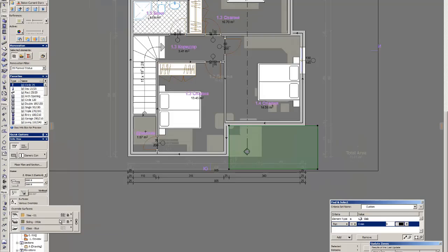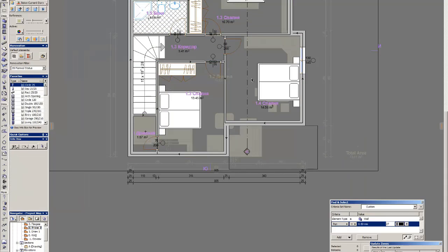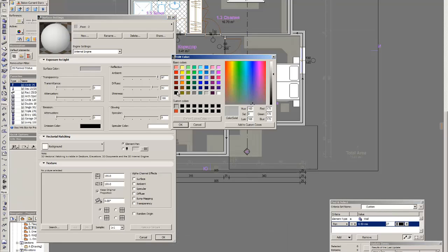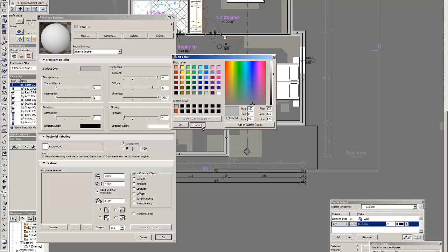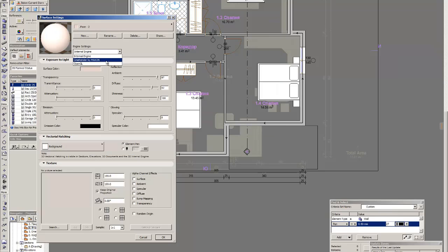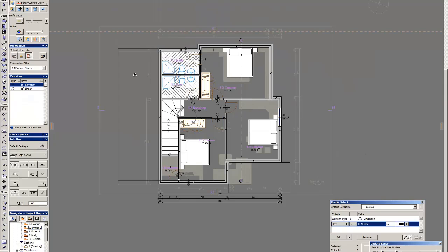We change the materials of all walls and slabs. Some walls we use phase 1 and others phase 2. We will change the phase 2 surface by going to our render, in this case scene render, and we will change the surface appearance and surface color also. That will make it more similar to the phase 1.